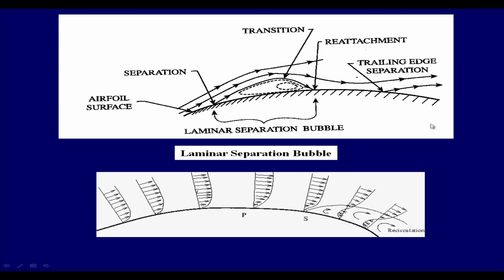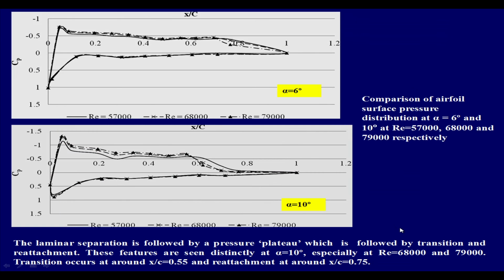And the whole physics is actually outlined over here, where you must have seen what is going on. As long as the flow is in the favorable pressure gradient, the boundary layer seems to remain quite robust, quite energetic. The moment it goes into the adverse pressure gradient, there is crisis, and then there could be flow separation and recirculation further.